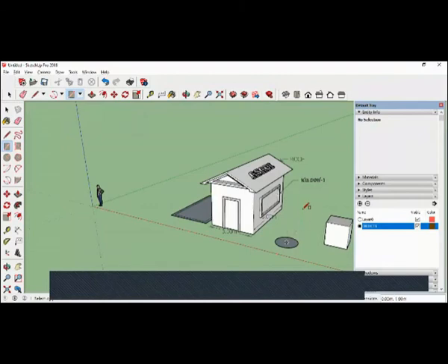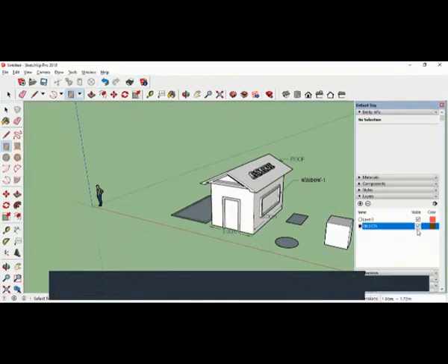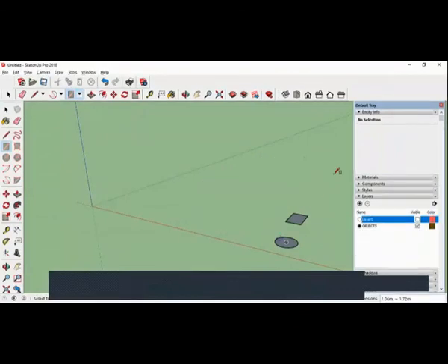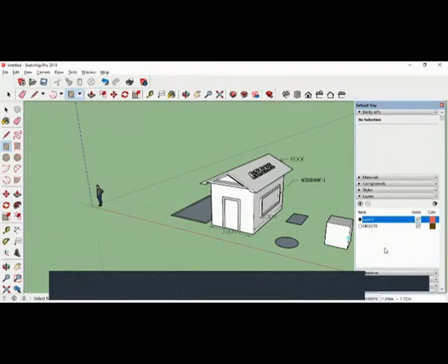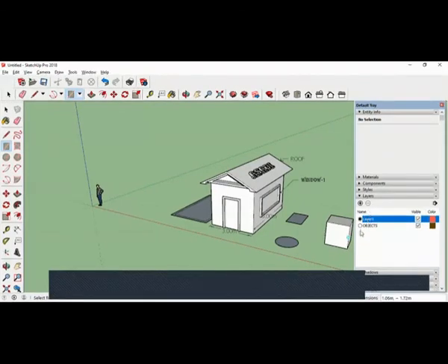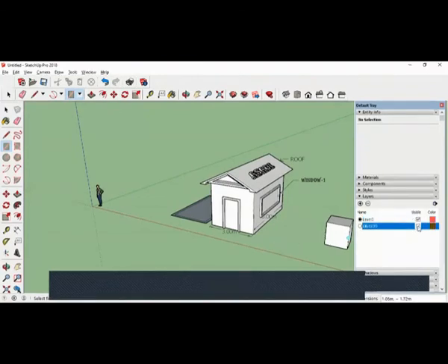See, if you are getting this problem, maybe use the top arrow. So these two objects are in this layer. When you are in objects, I cannot make it invisible. I can make this layer 0 invisible. I remove the tick mark. So all the objects in that layer 0 have become invisible, hidden. I can bring them back. If you want to hide this one, you go to the next layer. The current layer cannot be made invisible. Go here and now we can remove the tick mark.